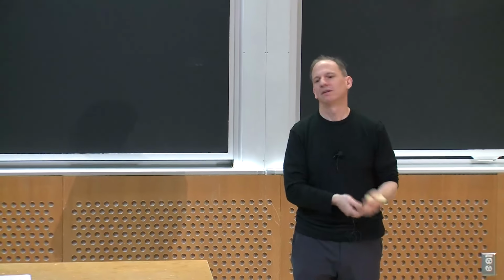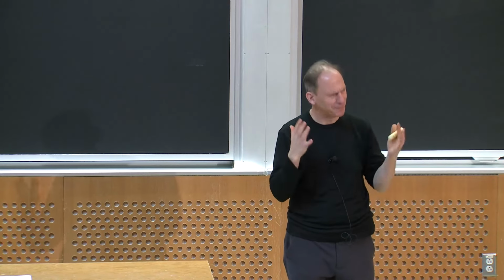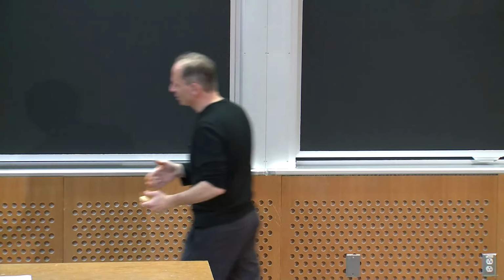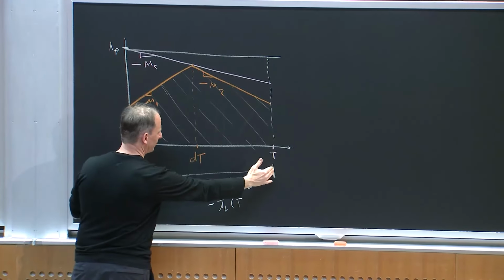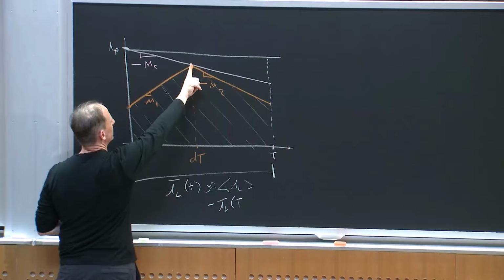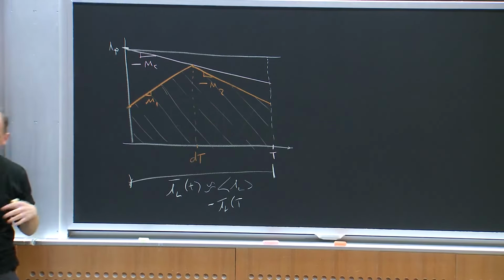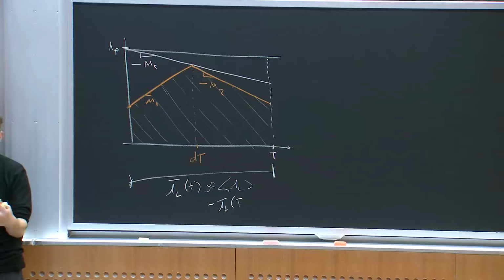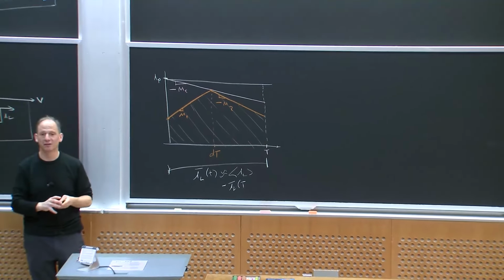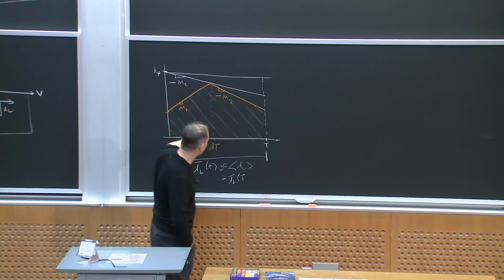All right? Now, if I wanted to be really theoretically pure about this, instead of looking over this window, which is centered at 0.5 T, I might look at a window centered at DT, and it would extend into the different switching cycles. But it turns out for practical purposes, for most cases, you more or less get the same thing. So the approximation I'm going to make is good enough given all the other approximations in the system. Okay? So I'm just going to average it over this window.